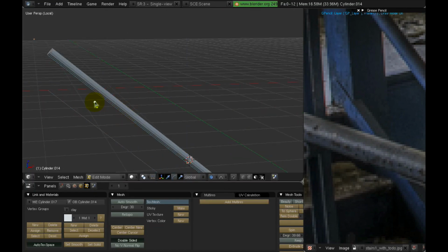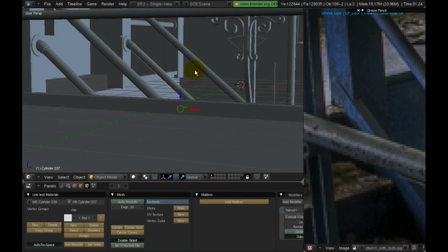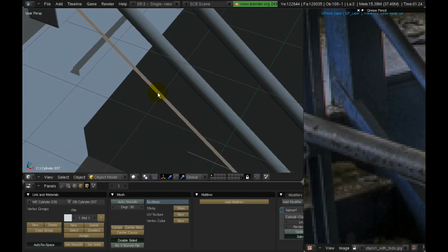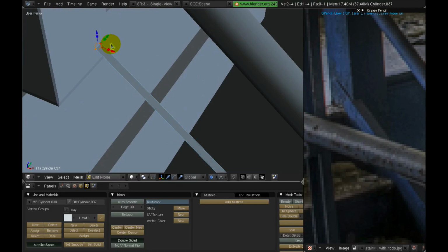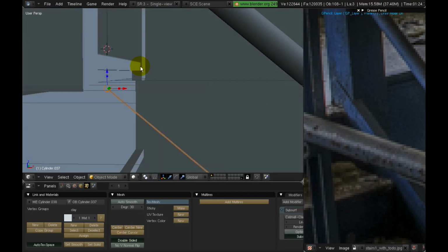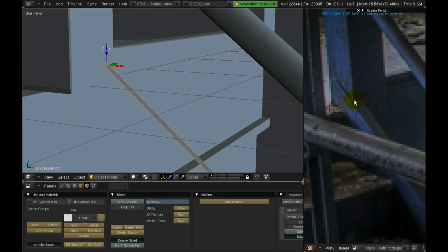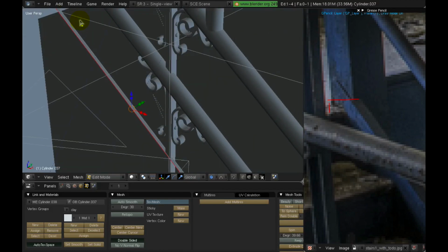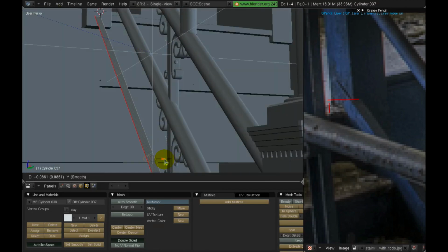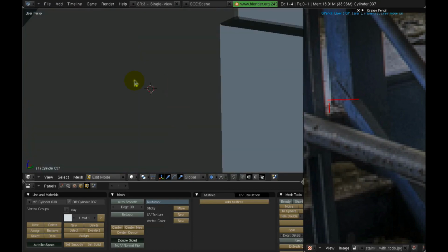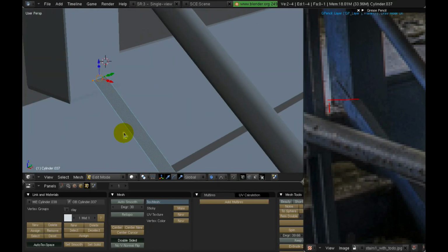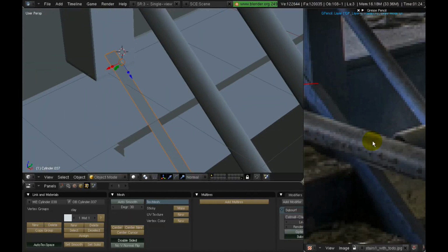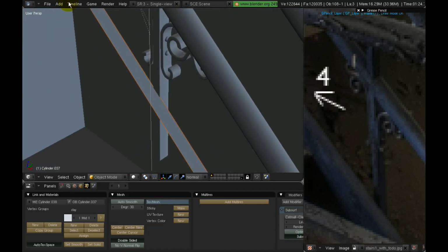And we want to start by duplicating a face in one of the railings, the bottom face, and pressing the P key to separate it into its own object. And that way we don't have to worry about making it parallel to the railing. It will already be set up the way we want it. And we want to pay attention to the relationship of the different parts to the post and the landing area, and also how it sits relative to the railing